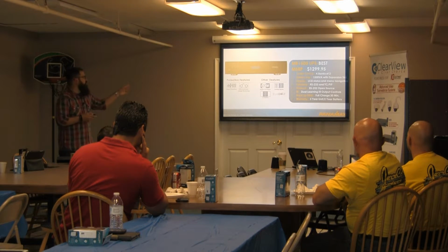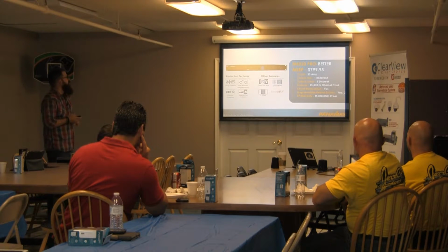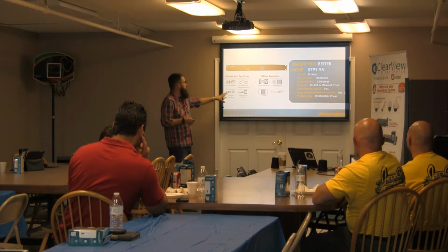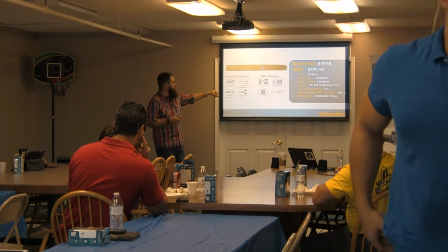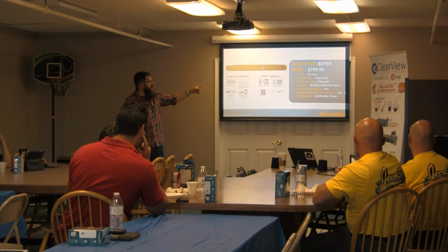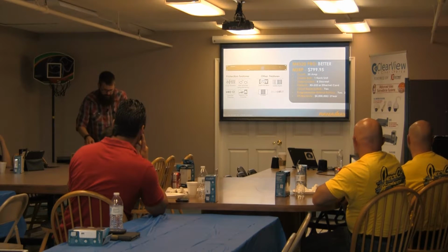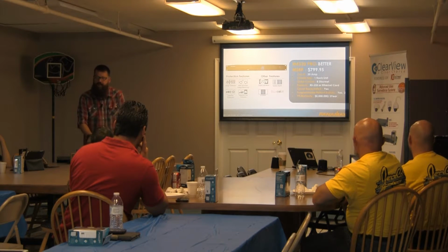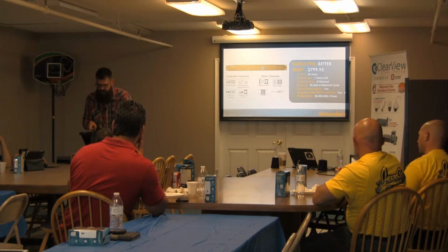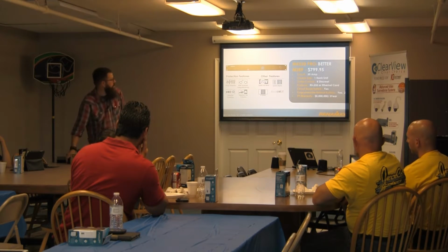If we look at the 1500, we've gone through this, we won't do that again. The 4320, it's got the surge protection, the AVM. We've talked about this till we're blue in the face. You guys all get it. Cable protection, telephone, LAN protection, 9 outlets, 8 discrete on the back and 1 on the front. Built-in sequencing on this unit. When you power this unit up, you'll see the lights go across, turns on outlet 1, then outlet 2, then outlet 3. They're not all going on at the same time.